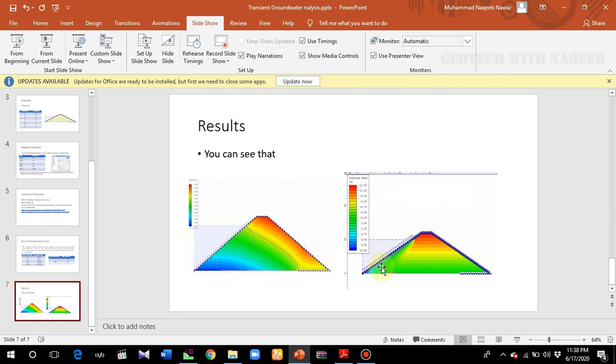So now here is the saturated zone and there is the unsaturated zone. Due to the difference in pore water pressure and pore air pressure, the water will be sucked by the unsaturated zone. It will try to create the equilibrium condition. Water will be sucked by the unsaturated soil from this zone towards this zone. So this function is defined by the soil water characteristic curve because this phenomenon depends upon the pore water pressure and permeability of the soil, pores of the soil, textures of the soil.